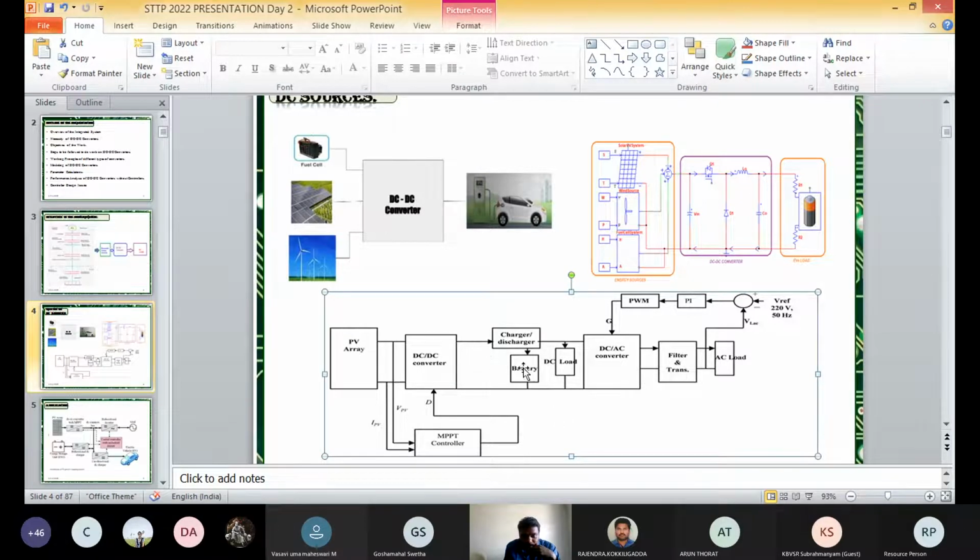And then, by connecting the electrical vehicle battery, we are using the DC power, and for the excess DC power available with us, we can convert the same DC to AC. While converting DC to AC, we get some harmonic components. To filter that out, we are using some filters, and then we connect the AC supply to the AC load. To get the desired output, we are forming a closed loop system. Later we will discuss how to design a controller for that.